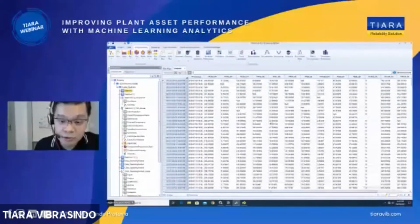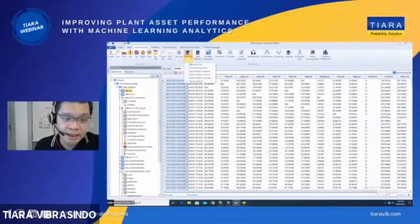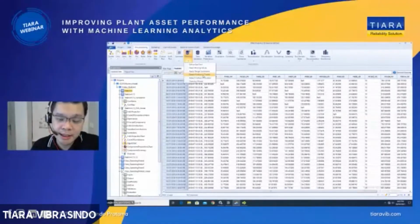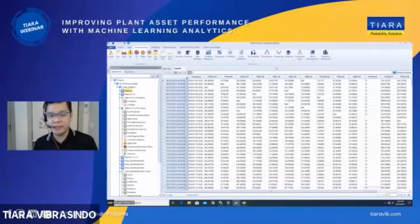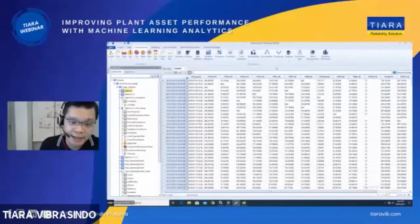These are the missing data, and there are also some funny data that can come out from time to time, like suddenly this value becomes very high compared to the rest. The software has a lot of algorithms inside to help you detect all these outliers, what we call dirty sensor data. We need to clean them out. Either you clean it up, or you smooth it out, or you can apply sampling and statistical algorithms to reason out the actual value.